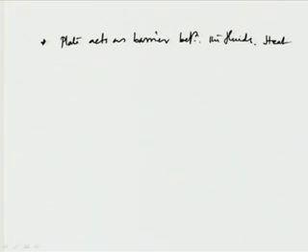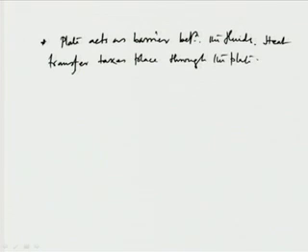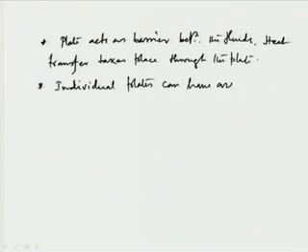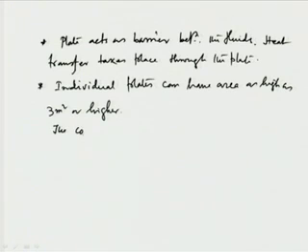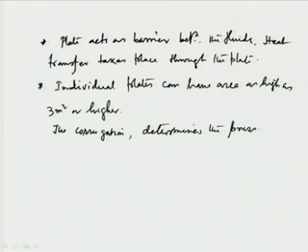And heat transfer, as I told, takes place through the plate. Individual plates can have an area as high as 3 meters square or higher. The corrugation determines the pressure drop and the heat transfer coefficient.